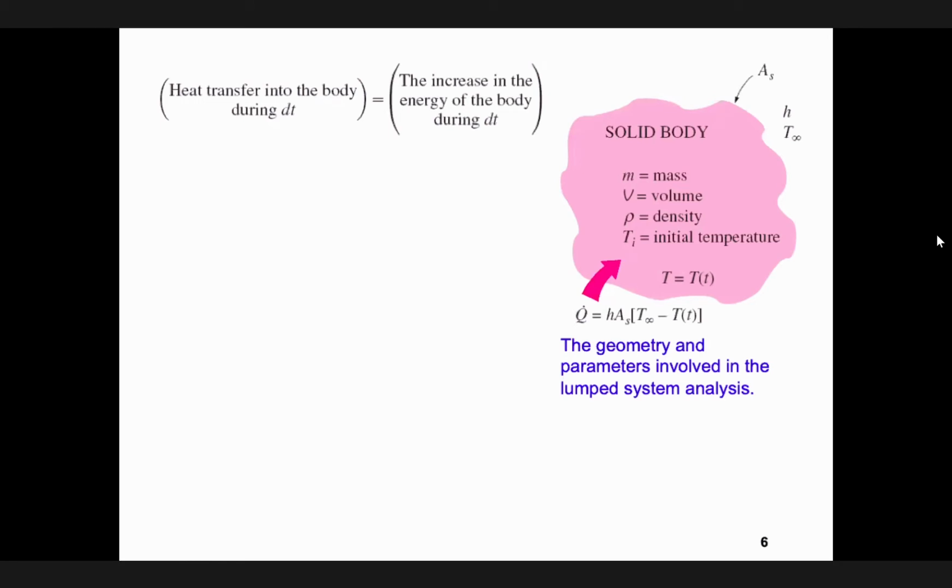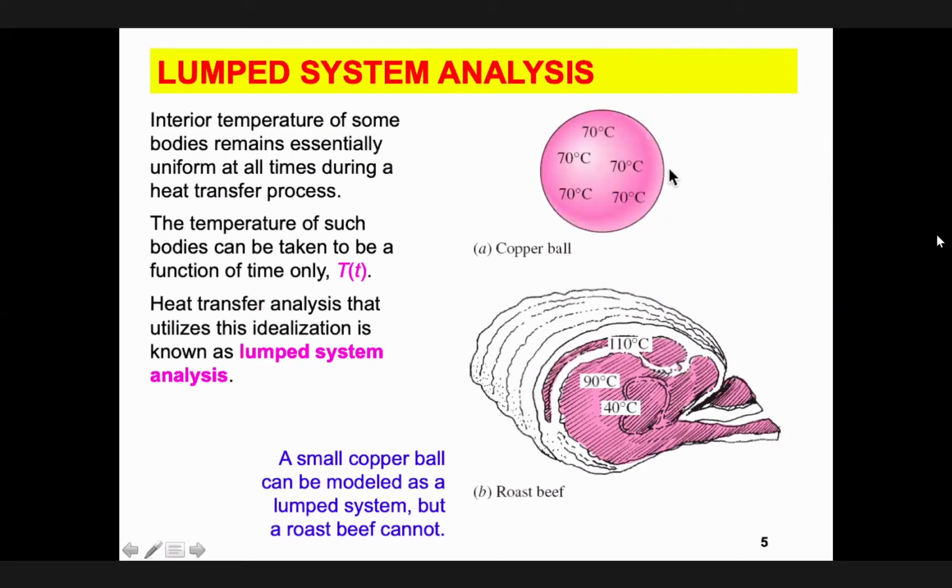Therefore, if I want to do it, look at here, imagine that you have, again, I'm trying to write a simple energy balance, okay? Keep in mind that I assume there is no conduction in the wall. There is no conduction in this ball. Temperature everywhere is the same, okay? Ignoring the conduction, you have convection and then some energy.